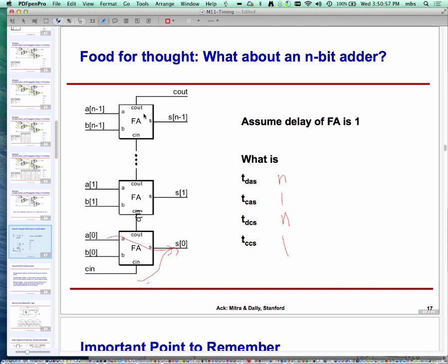So it turns out that in modern circuits, if your propagation delay is too much, I can take care of it by slowing down the clock. At some slow enough clock speed, the propagation delay is going to be taken care of. Contamination delay becomes very nasty because if I have very short paths through my combinational logic, then they may reach the flip-flop while the flip-flop is still in that range where it wants the input to be stable.